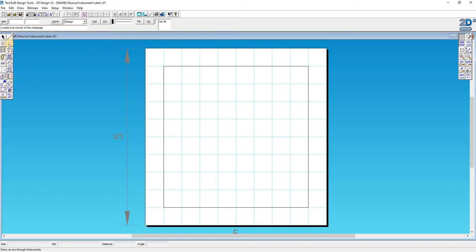So I am going to come to this Arcs tool over here in the top left. Now I'm going to call this tool B2. This Shapes tool I'm going to call A3. This is like referring to cells on a spreadsheet. So column A, row 3, and then here I'm column B, row 2. If I hold my mouse button down on that Arcs tool, then the toolbar expands, and if I move all the way along to the end, I've got the filleted arc tool.